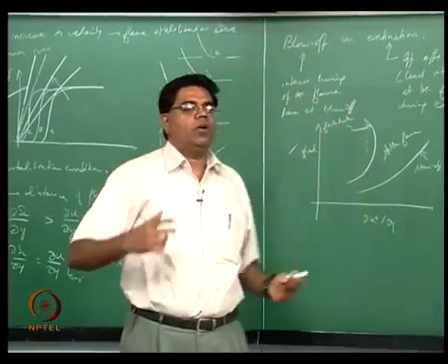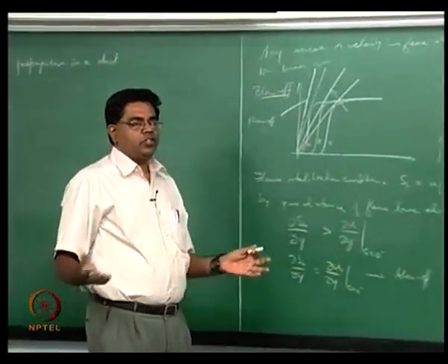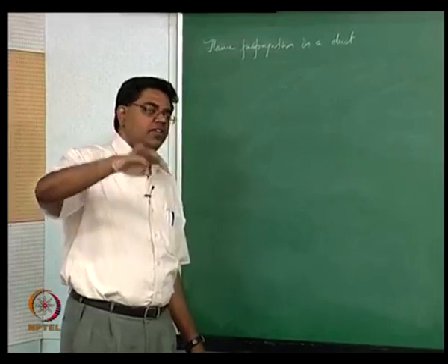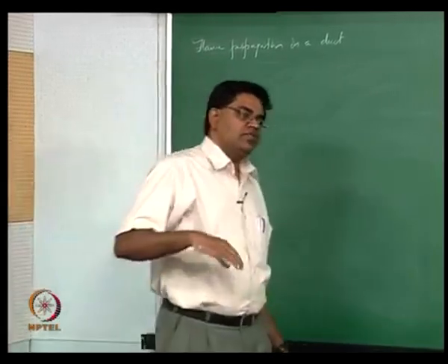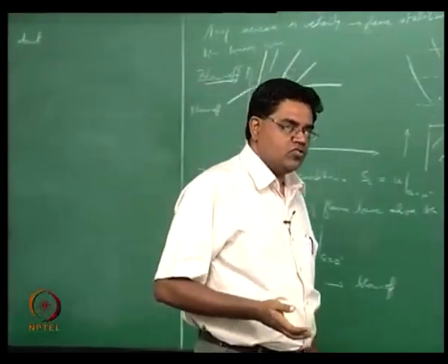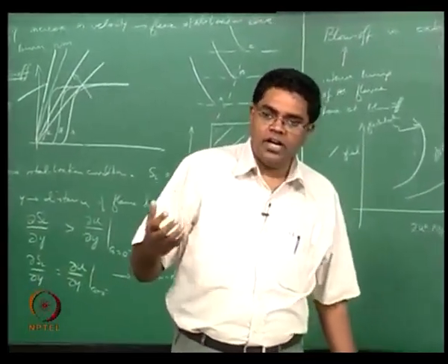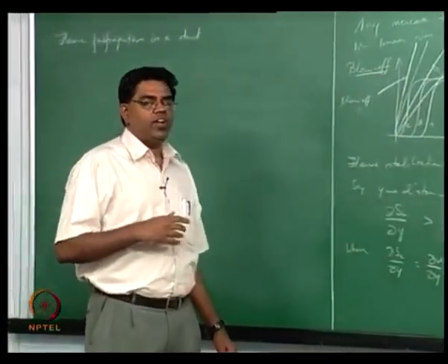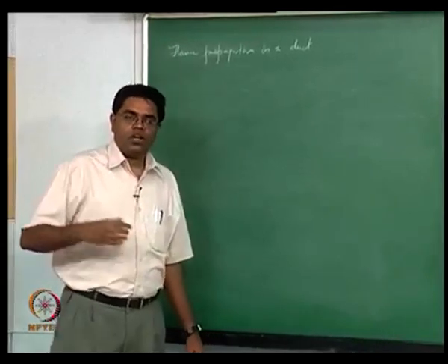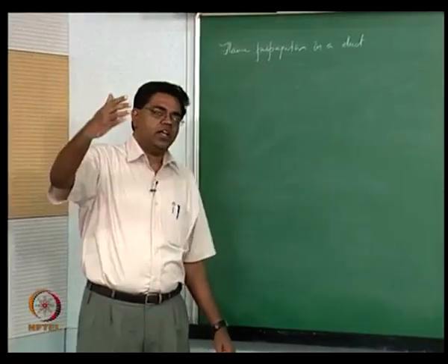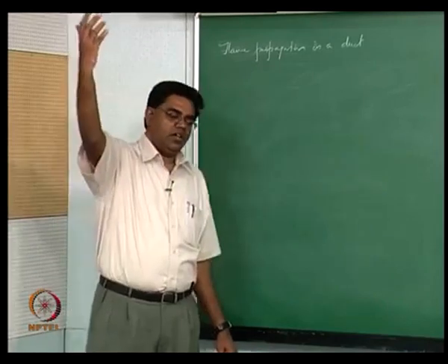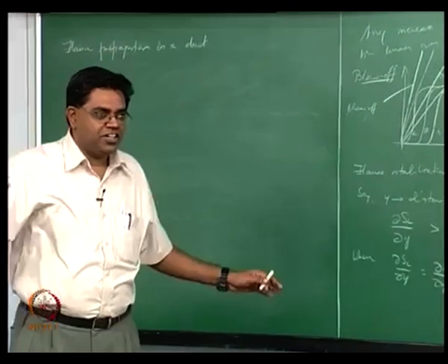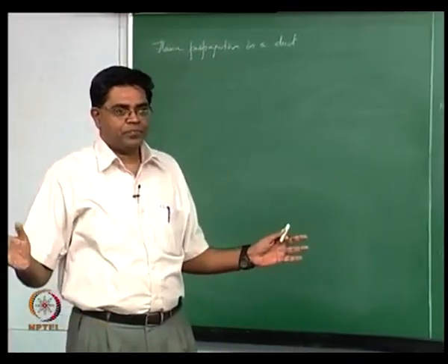Now implicitly in our minds we have been adopting a gravitational field that's acting on these things, and therefore there is an effect of buoyancy on these gases, where the lighter gases would actually go up and the denser gases would stay down, and the lighter gases are made lighter because of a higher temperature, mainly for the products, when compared to the colder gases being the reactants, and therefore denser. And so long as you now have a flame that is demarcating denser gases being down here and the lighter gases being above, that is where they belong, so nothing is difficult or different, right.